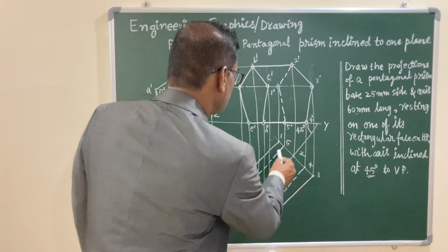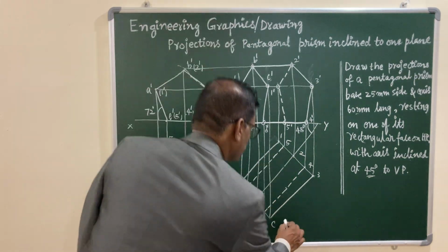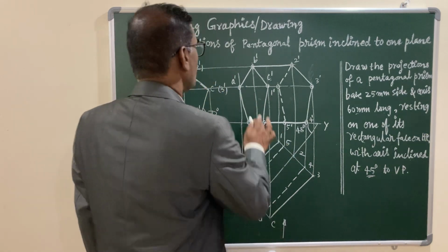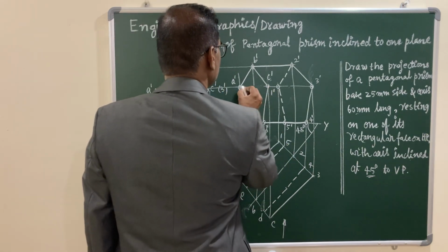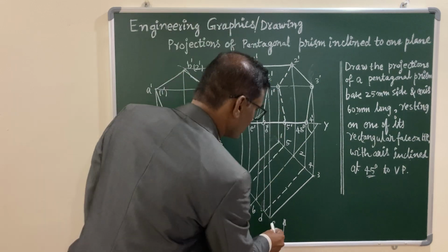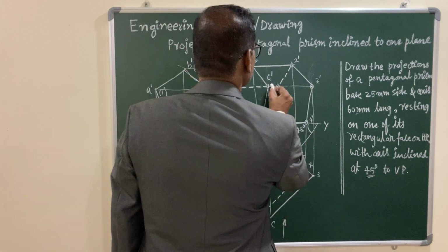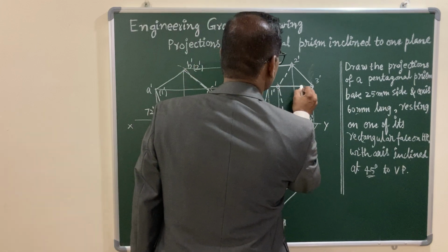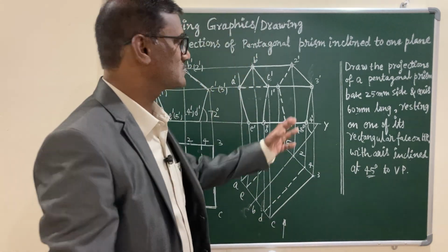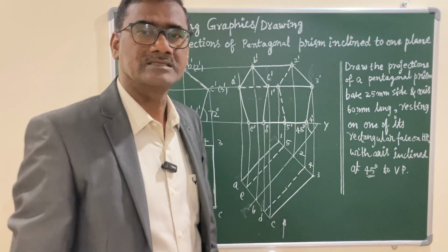Observe carefully that 1A is not visible in the direction of view, so you mark that edge with a dashed line. And C3 is overlapping with that, and it is completely visible. So this completes the projections of the solid with its axis inclined to one of the planes.